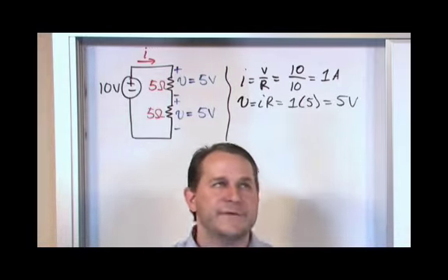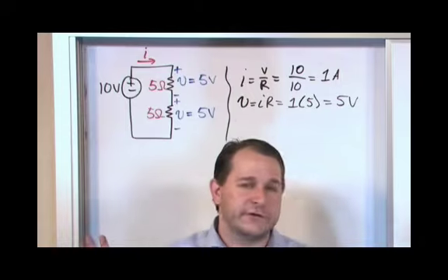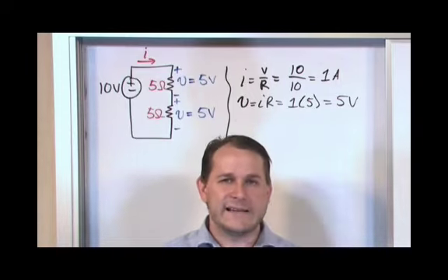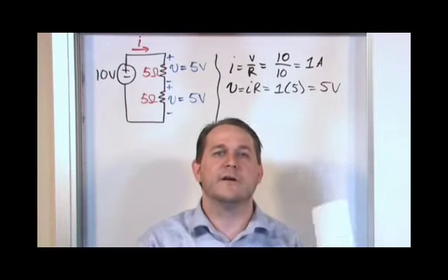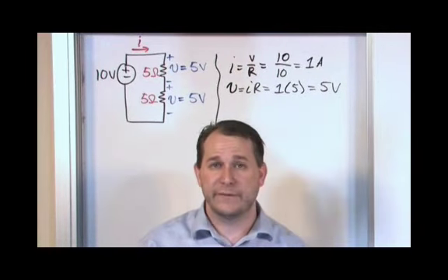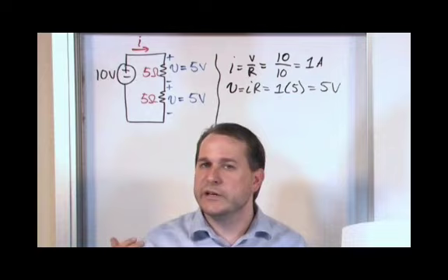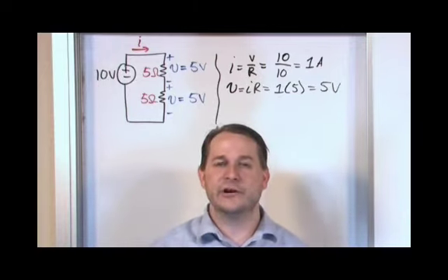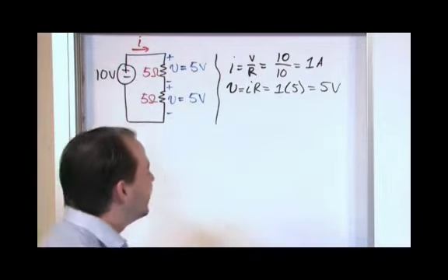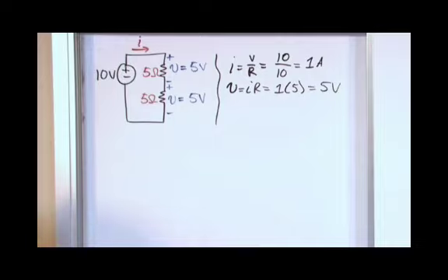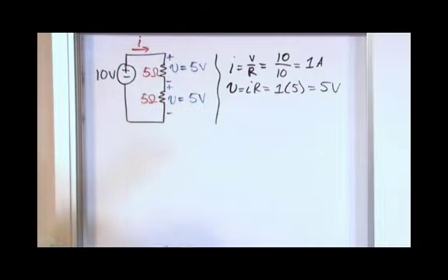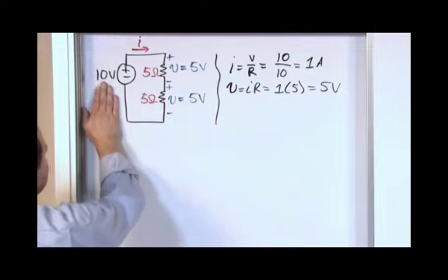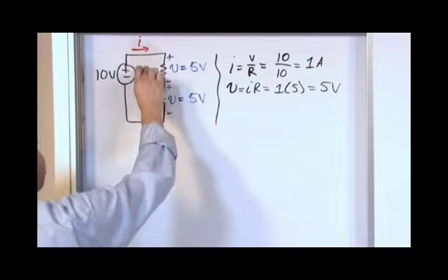You see, I'm not inventing something else, saying, oh, this is a special voltage divider, you just have to memorize it. It's not like that in circuits. Everything makes sense from the core values of Kirchhoff's laws and Ohm's law and the fundamental things we've learned. So there's nothing really new here. It's just an application of what we already know and some intuition that comes as a result. So this is the bottom line. If I want to divide this source in two, I would choose 2 equal resistors.